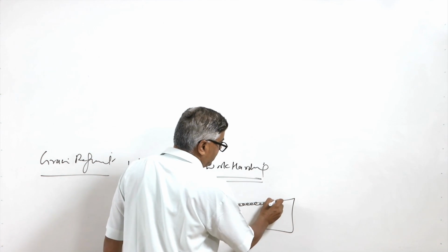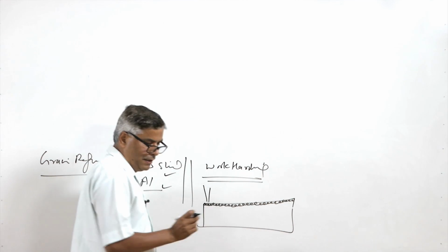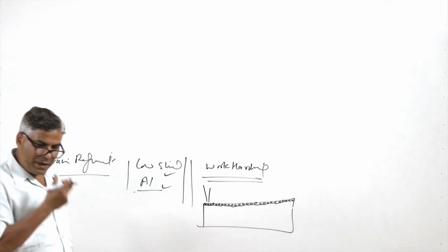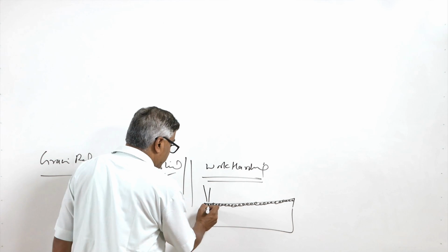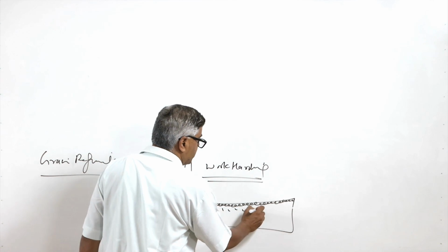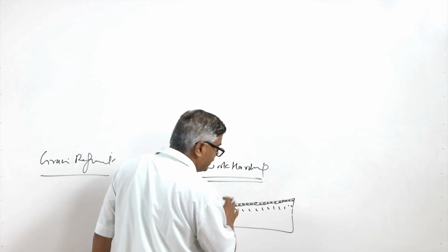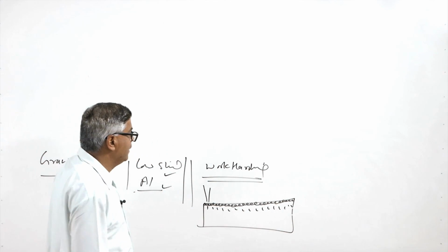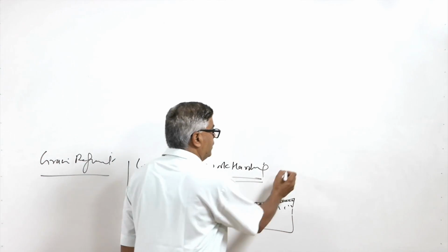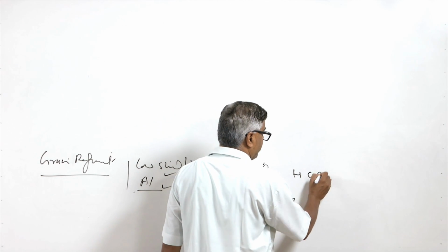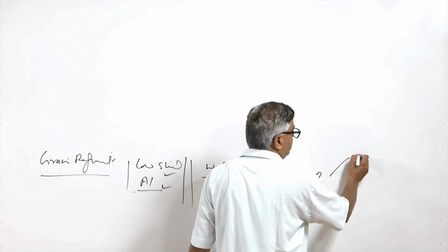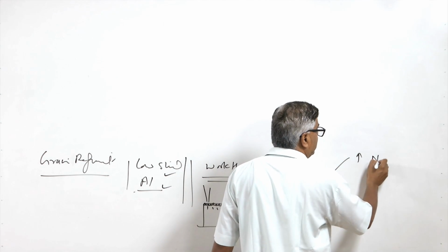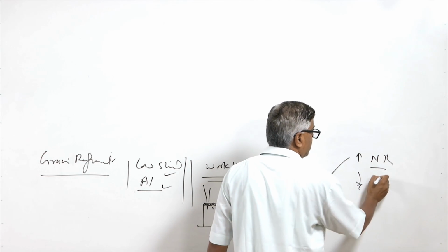Since the layer being melted is very thin, it is immediately quenched by the underlying base material, experiences a high cooling rate, and that in turn leads to a fine grain structure, because if the cooling rate is really high, it leads to an increased nucleation rate and reduced growth rate.